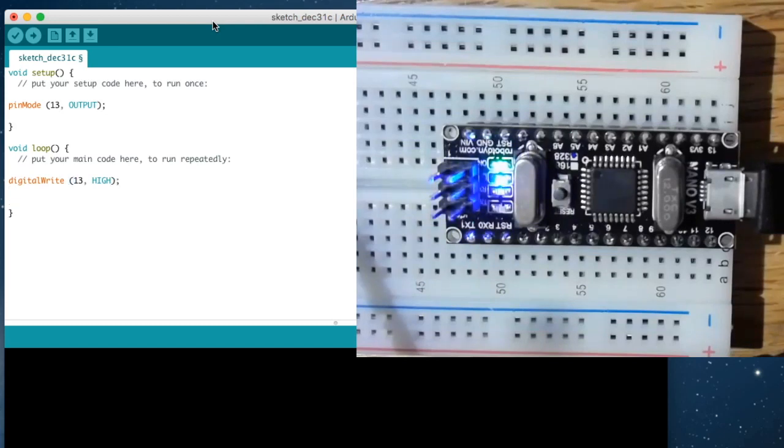Now, for those of you who don't have an electronics background, think of high as positive voltage logic. It's a signal. It's a digital signal. A pin is either high or it's low in digital electronics. For sake of conversation, let's say that high is 3.3 or 5 volts and that low is 0 volts. So we're going to say apply 3.3 or 5 volts, whatever is appropriate for this hardware, to that pin, i.e. set the pin high.